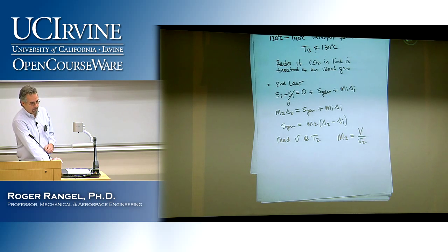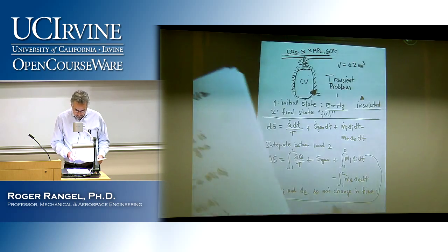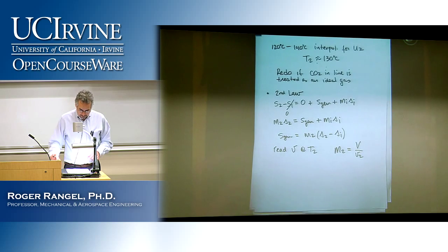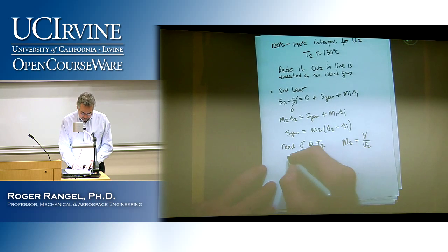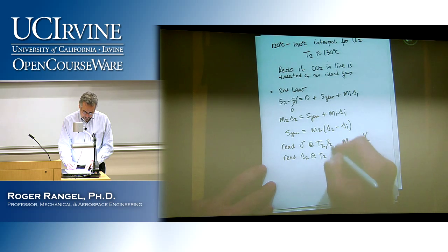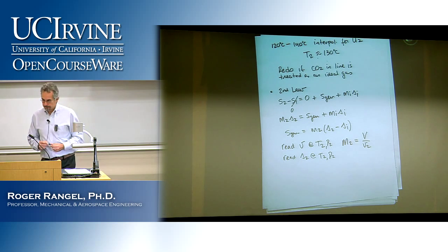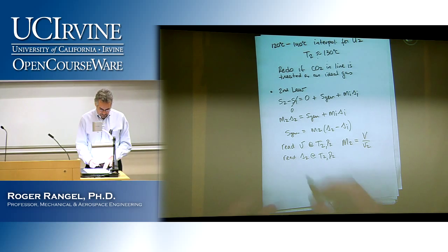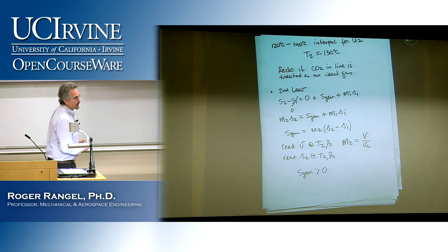Right? I can get that m2. s_i, I read it earlier in the table. So s_i was 1.477 kilojoules per kilogram Kelvin. And I can just go back and read s2 in the same table, so read s2 at T2, of course, it's T2, P2. So I can read that, and then I can get this number. And in this case, you won't get 0. You will actually get entropy generation. You should verify that it's a number that is greater than 0.